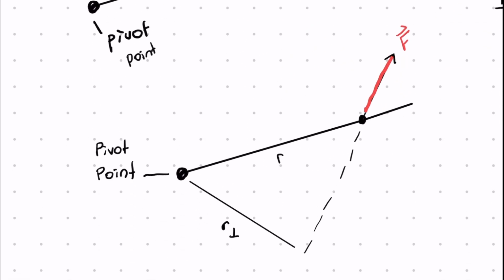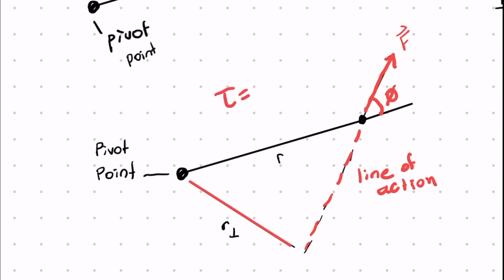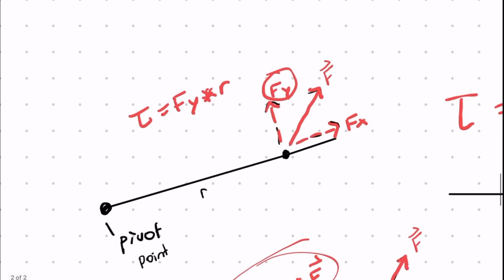Another way to find the torque generated is by altering the lever arm to become perpendicular to the angle of the force. The direction of the force can be extended as a line of action. Then, a moment arm can be extended from the pivot to the point where it intersects the line of action at a 90-degree angle. The moment arm's length will be smaller than the actual lever arm and is the only one quantity relevant to the equation.